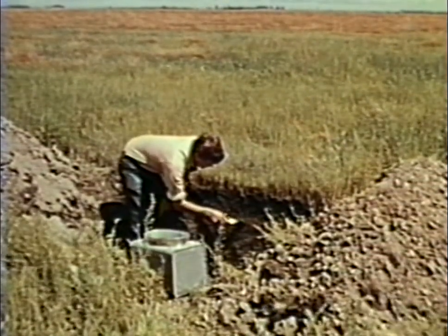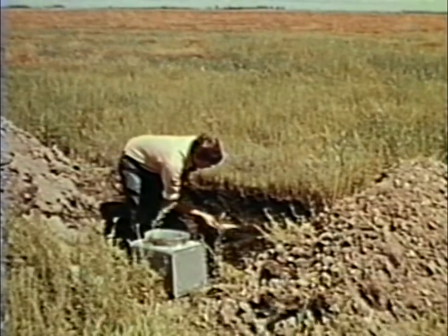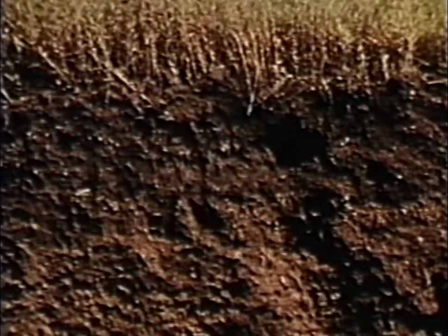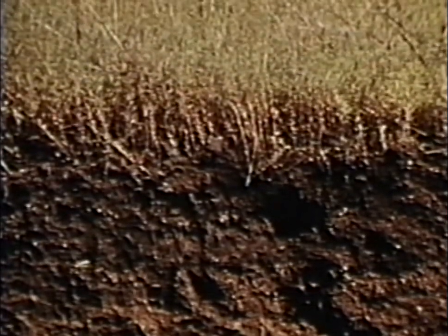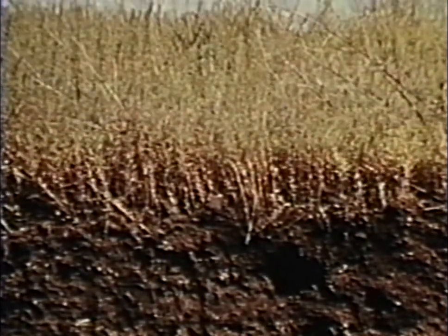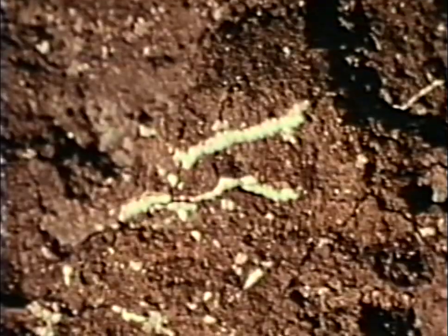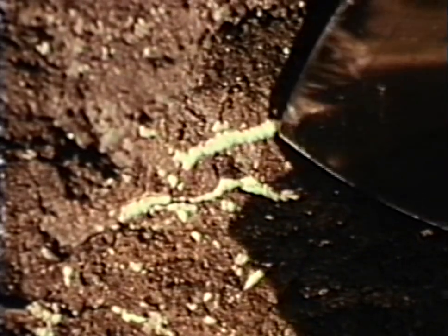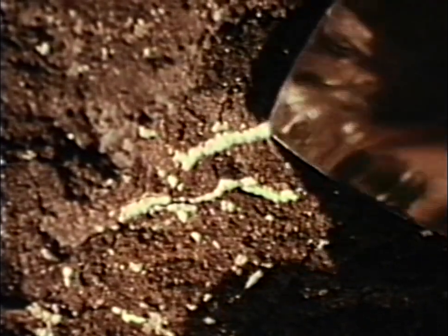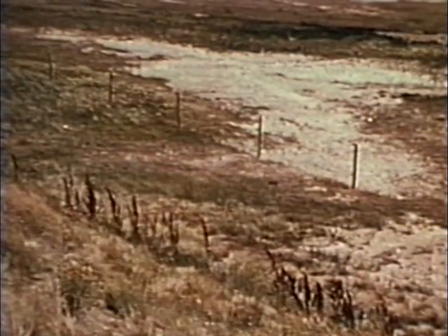This site is in a groundwater discharge area where the water table is shallow. Salts are brought to the water table by groundwater flow and are then carried upward into the soil by capillary movement. As the soil water is lost to the atmosphere by evaporation and plant use, the salts are left behind. Gradually, saline soil zones develop as the salts occupy an increasing portion of the pore space in the soil. Eventually, the salt may prevent the soil from supporting plant growth.